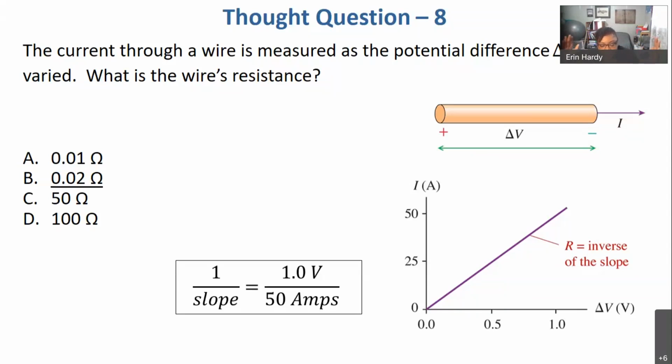And if we think about that trip between, let's say, your nearest power station to your nearest substation to the nearest transformer near wherever you are right now, there are some benefits to either scaling up the current while making the delta V relatively small or doing the exact opposite. And what you are trying to achieve in playing around with those current and voltage values is to minimize the impact that this wire's resistance has on the amount of energy that you're moving from one place to the next.